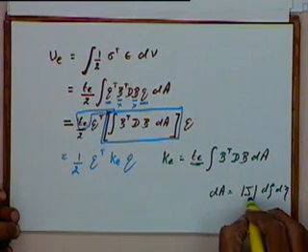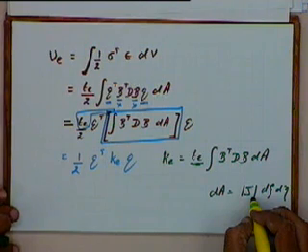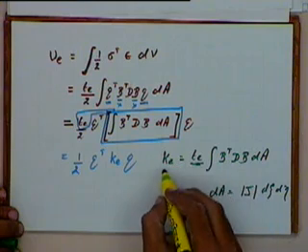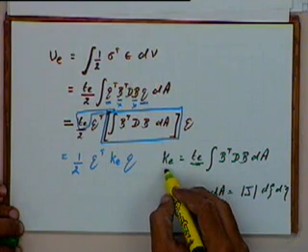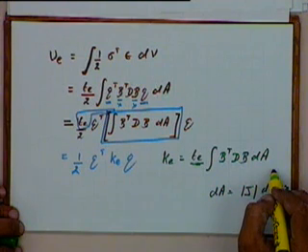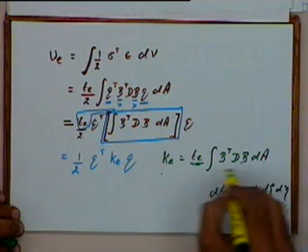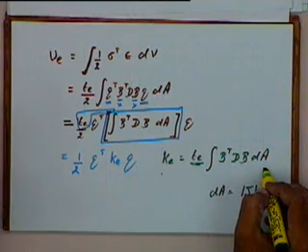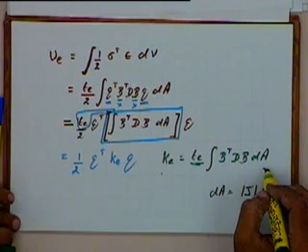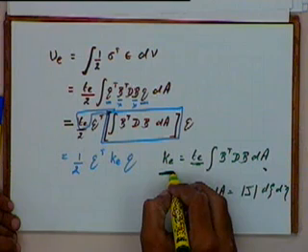So this determinant of J will again have terms of zeta and eta, and the stiffness matrix can only be computed by carrying out this integral using numerical techniques. So for finding out the stiffness matrix in the case of a 4-noded element, one has to carry out this integral using numerical techniques, and only then we can get the values of the stiffness matrix.